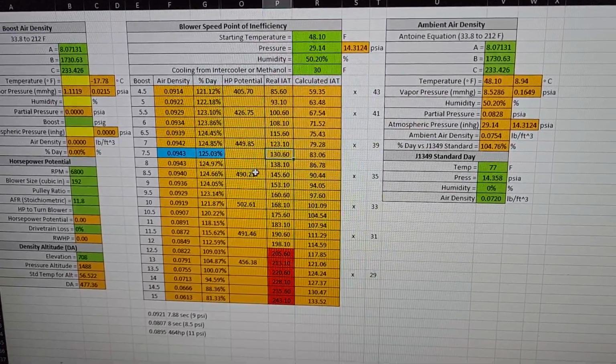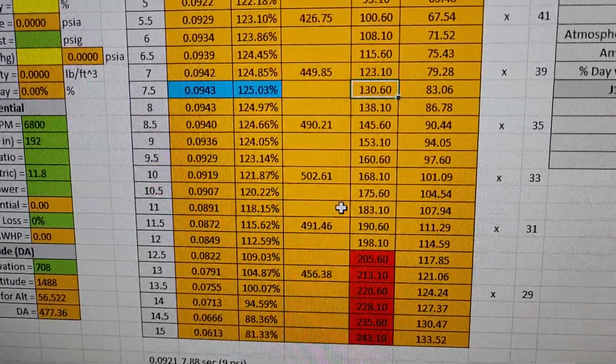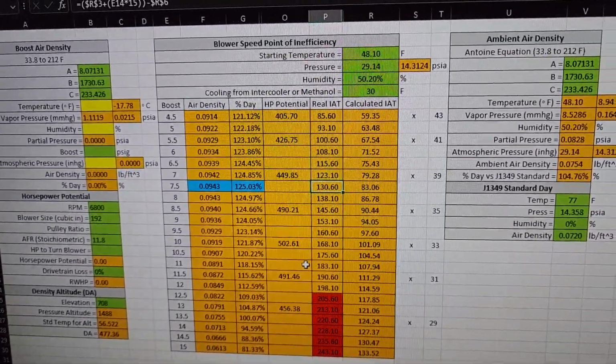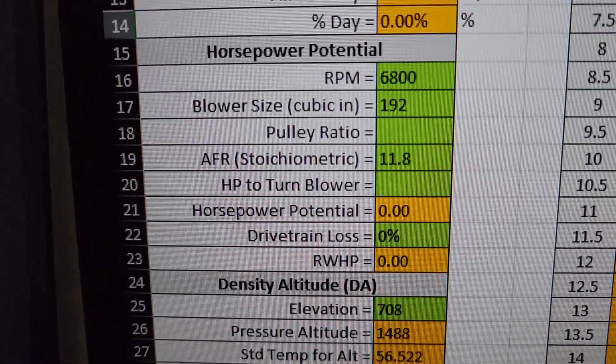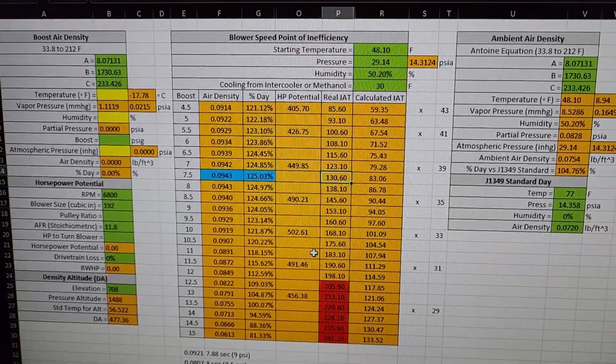And so these numbers can actually get even worse because you're pulling a lot of timing. These horsepower figures are with perfect timing. You are using all the fuel. This 11.8 to 1, you're using all that fuel to make horsepower. And that's not always true.